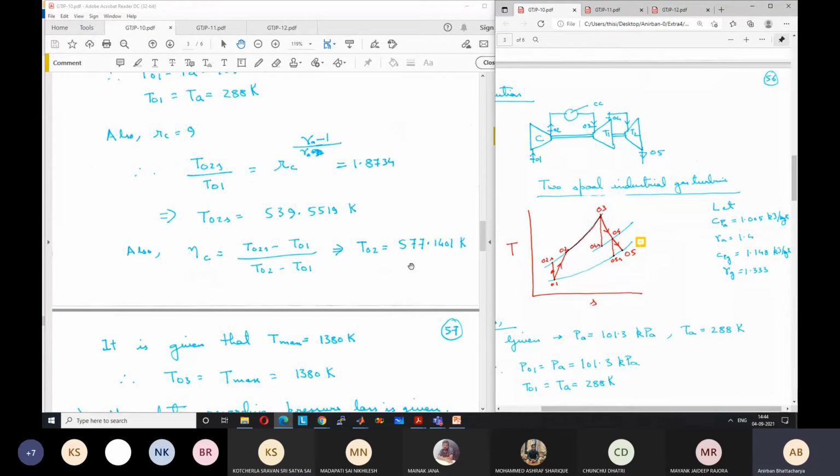So you can see that even at the compressor outlet, the actual temperature is quite high, but relative to the other locations, the temperature is actually low. So this air is actually used for cooling the turbine blades. In this case it is not considered, but in actual cases, you will need cooling air for the turbine. It will go from the compressor outlet, and the typical temperature will be somewhere around 550 Kelvin, so around 300 degrees centigrade. But still, it is sufficient to cool the turbine.